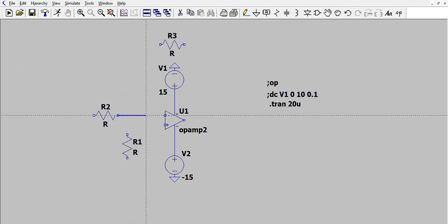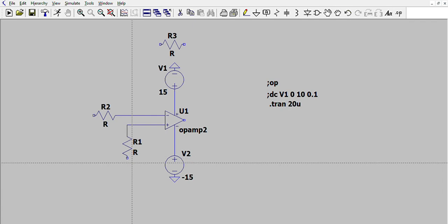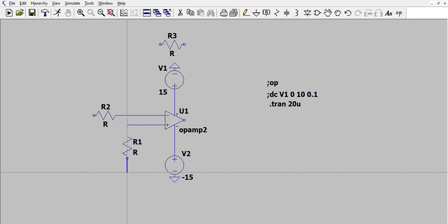I just performed your in-lab assignment, which you did in the 4th week, I guess. You have a gain of 10 as an inverting amplifier, and this one is 4.7k ohm. The value of this one is 5.6k, and the value of this one is 56k.